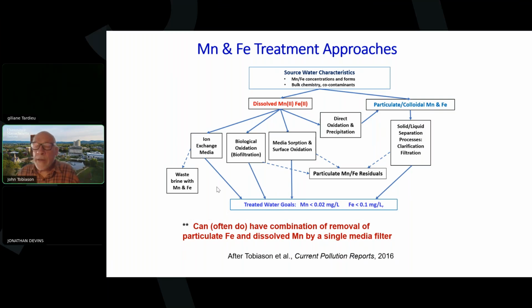A process I don't list here is membrane filtration, RO or NF. Those can remove manganese or iron, but manganese or iron basically destroy, clog such processes. So they're never a primary objective at a commercial scale. Point of use is different.